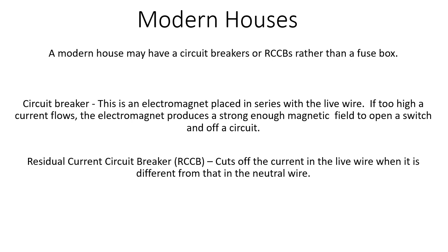An RCCB, or a residual current circuit breaker, constantly monitors the current travelling through the live wire and the neutral wire. It will then cut off the current when the live wire current is different from that of the neutral wire.